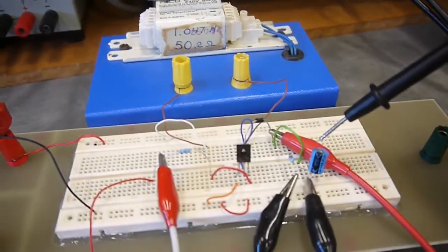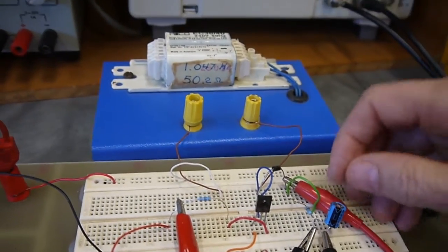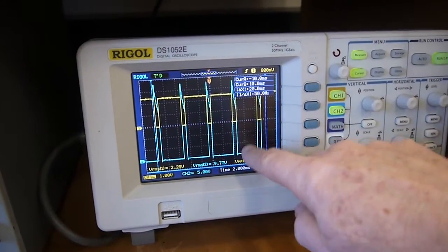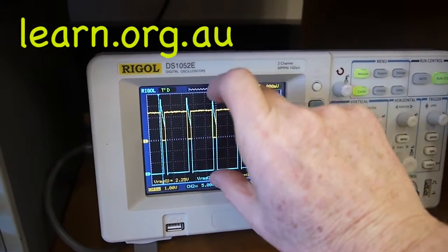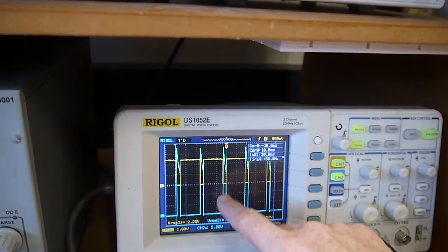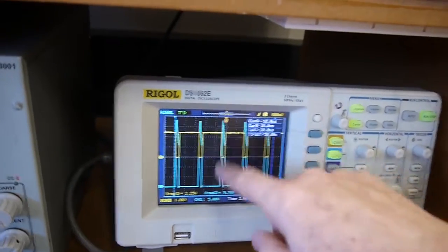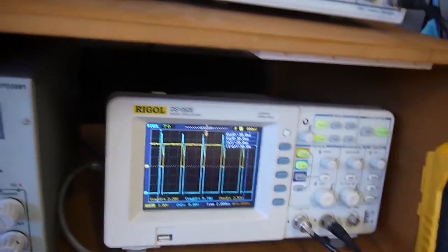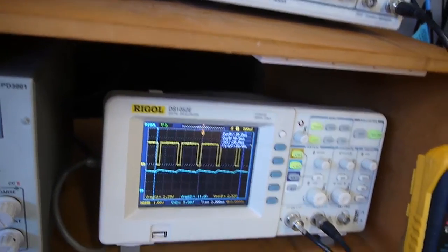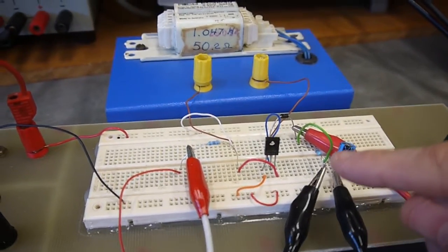Out of our circuit, there's a small electrolytic capacitor here. If we take that out of circuit, that has a dramatic effect on the amount of ripple, of course. The ripple has dramatically increased to some quite high voltage spikes here. 5 volts, so 5, 10, 15, 20, 25, 30, 35 volts of voltage spike there on the output. So that's quite nasty. If you had higher voltages involved, you'd certainly have some bad things happening there to components on the board if you took away that output capacitor.